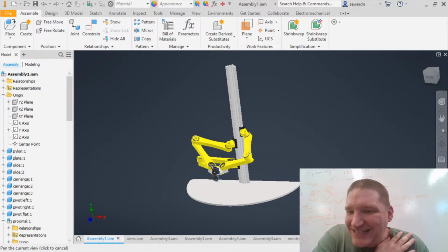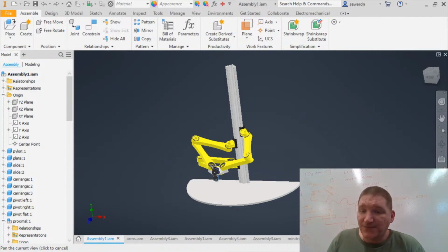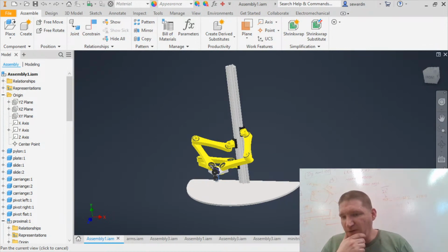Let's see, Waffle Beaumont: instead of using a linear rail, which might bend down a little, as some people have mentioned, I think that maybe two smooth rods separated by some distance might give more rigidity. This might be a counterintuitive thing, but long round rods are very, very bendy.